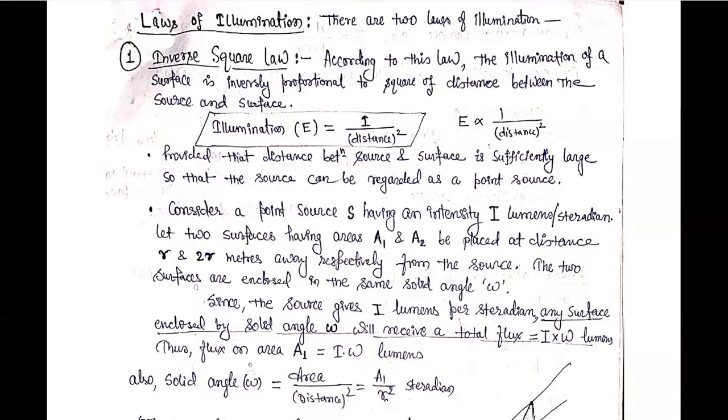इसका मतलब है illumination क्या होगा? किसी भी surface पे अगर आप किसी लाइट को ऑन करते हैं और कहते हैं कि ये हमारा टेबल है, वर्किंग प्लेन है हमारा, यहाँ पर illumination क्या होगा इस लाइट सोर्स का? So that illumination you can define with the help of this inverse square law. ये लॉ कहता है कि जो illumination होगा उस वर्किंग प्लेन पर due to a light source, that is inversely proportional to the square of the distance between the source and the surface.